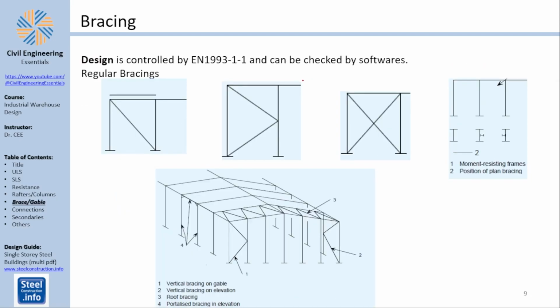What about bracing? I have done this in Autodesk already, but the reference gives more details. You can single brace, V-brace, cross brace, and even use a fully fledged moment resisting frame. Of course, I am more a fan of those stabilizations. I'm not a fan of using a fully fledged moment resisting frame. Why? Because it will cause all kinds of complications here.